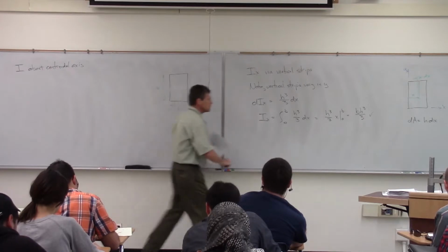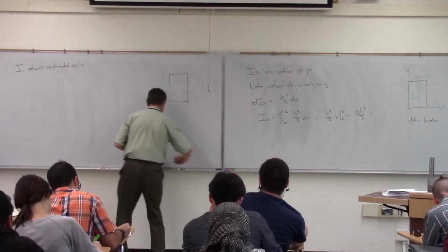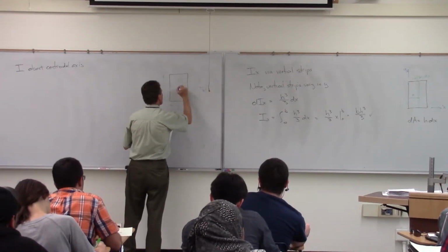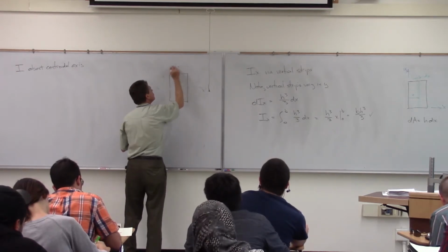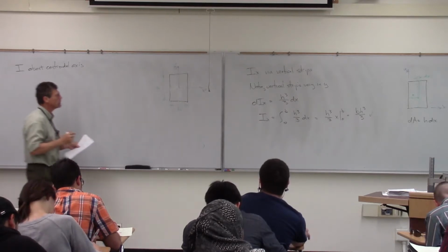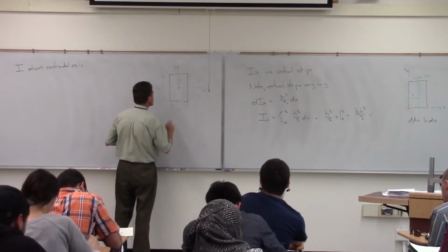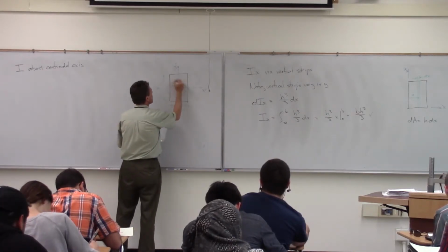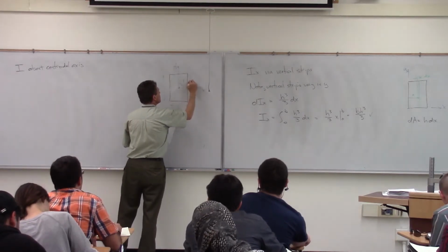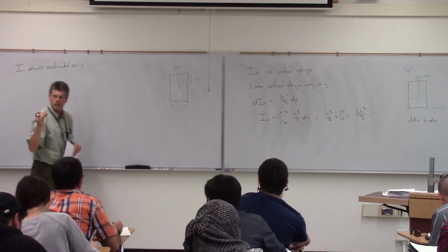But what I'm going to do a little bit differently here, and your author likes to use prime to indicate that we're using a centroidal axis there. So we know the centroid of a rectangle is going to be in the center there. So same approach, except that what we're going to do now is look and calculate this about the centroid.